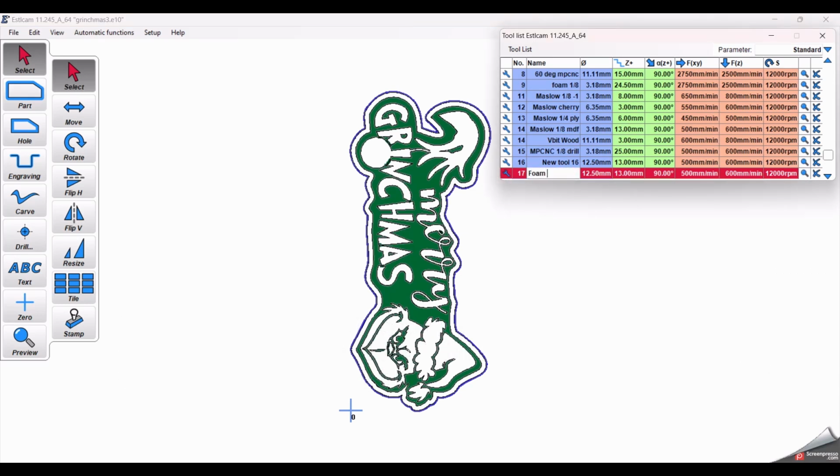It should be a 2 flute straight bit, a vertical bit with 2 flutes. It's actually 6 millimeters, and so I put 6.35. The total Z depth is... I put 52. One and a half only needs to be 38 and a half. We're gonna run it as fast as we can, so 3,000 would probably be okay, and then plunge at 800.